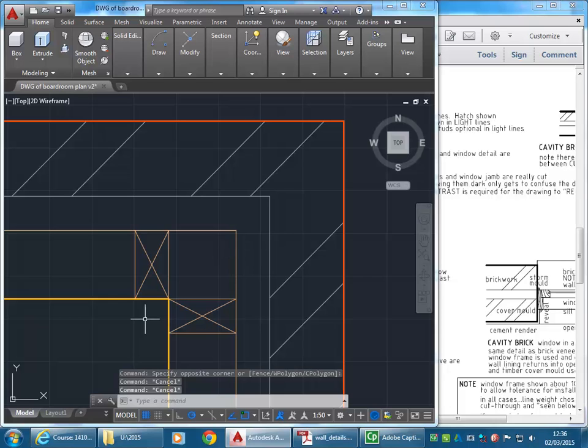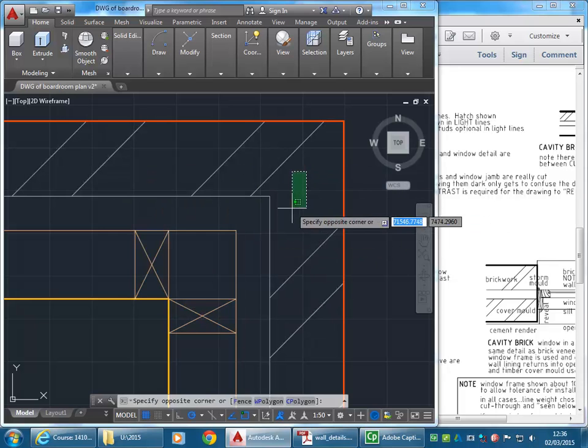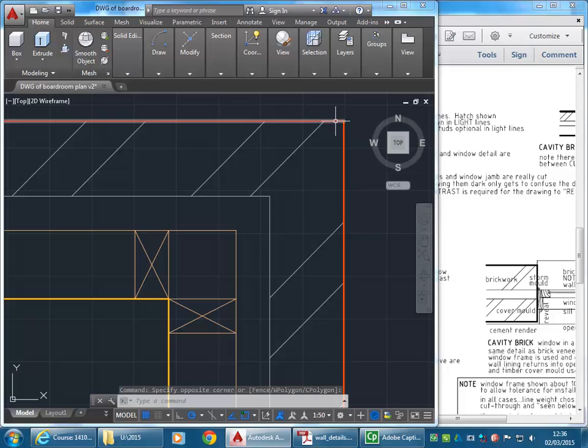That's a nicer way, and then you're following true drawing convention, having the outline of your wall with a heavy line weight, and then all of those internal parts with a lighter line weight. If you're wondering, they're 0.35 on the outside, and the inner lines I've just made 0.25.